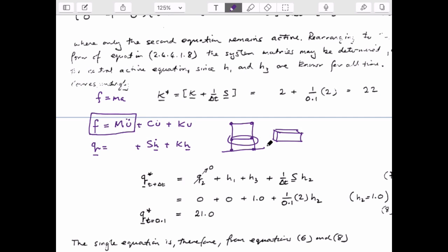And all that you do is put a mass on each of these beams for this element here, lumped at that particular location, and a mass here, and it would just be equal to half of this mass applied on each. So that's where the word lumped comes from. You lump the mass at one location.